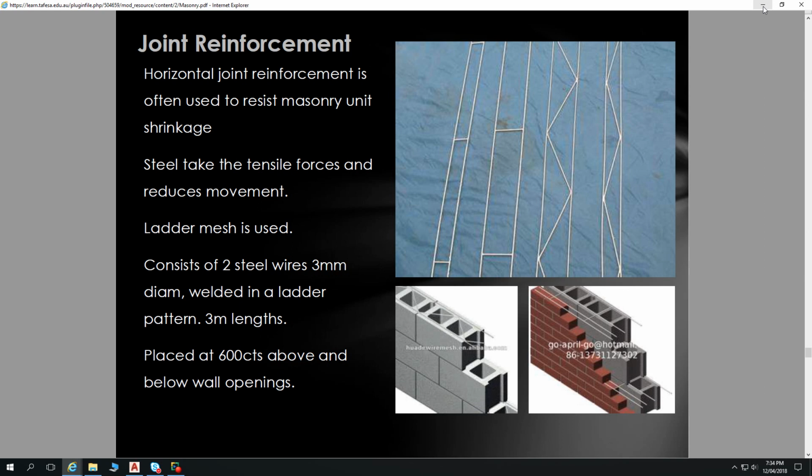The reason for that is they've used concrete bricks, so smaller concrete blocks that were relatively fresh. They hadn't shrunk down yet, and then with new mortar as well, and that shrinks. So the bricks were all laid, and then the walls just shrunk like that over a fairly short period of time. So that's a fault of the manufacturer of the bricks, that they sent the bricks out too early. They hadn't sat there for long enough to shrink down correctly.